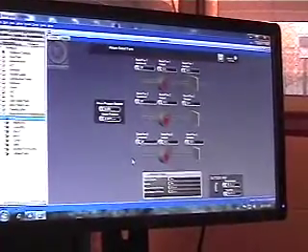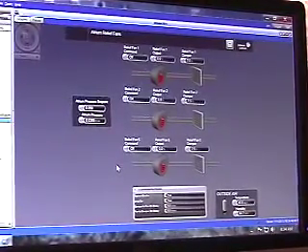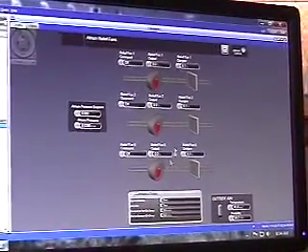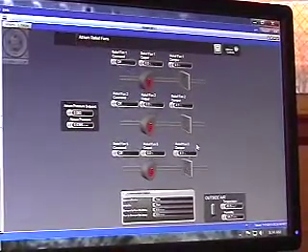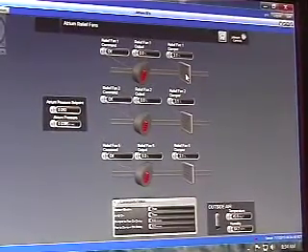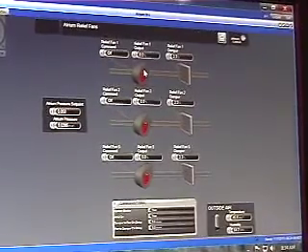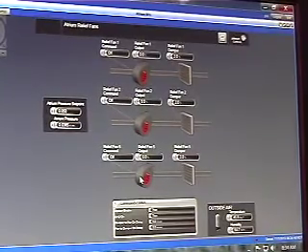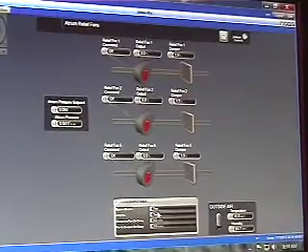The way this works is when the air handler that's associated with this area, which I believe is air handler 1, whenever that's running, we enable the relief fan system that has the ability to run. The first stage is going to modulate the dampers up and down to maintain its set point. Once these dampers become fully open, 100% open for, I believe, right here, fan delay is 5 minutes, it'll then enable the relief fans to turn on. The relief fans will then turn on and modulate up and down together with that. Real basic.